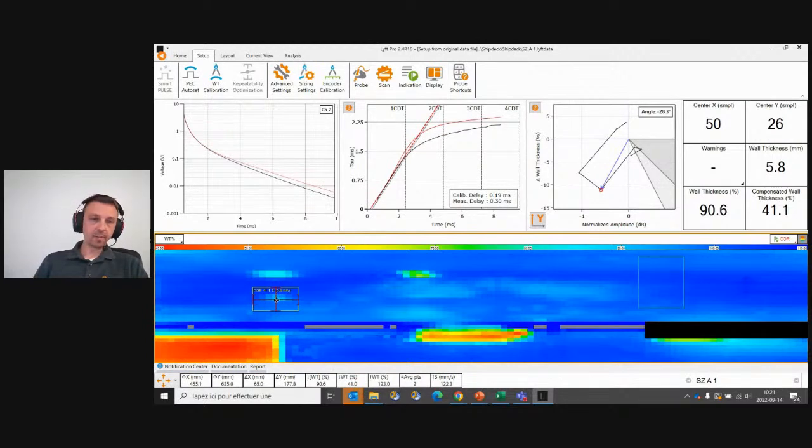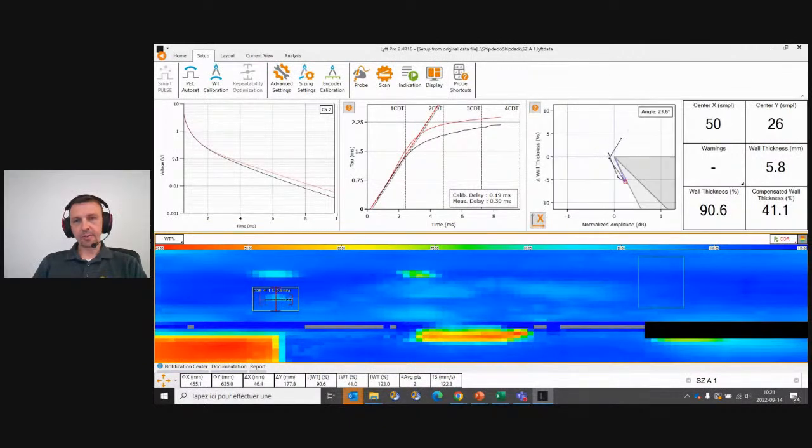It's a little bit oversized, but again, if we close the data selection on the Perm tool a little bit, we can see that the Perm tool vector will start from the uncertainty area close to the false positive indication. And if we increase, the vector now goes in the true wall loss area. Which means that probably we have a little bit of effect on the change of properties related to the heat affected zone or the manufacturing of the defect.